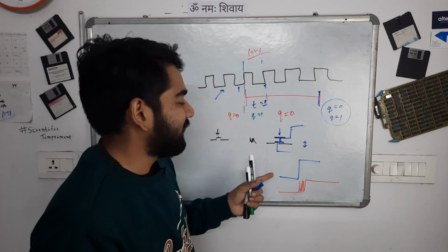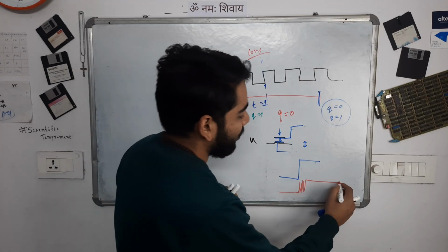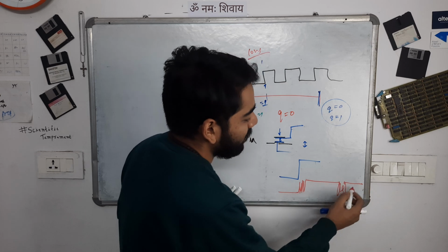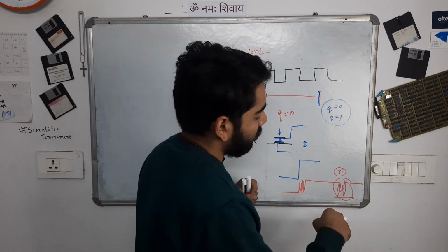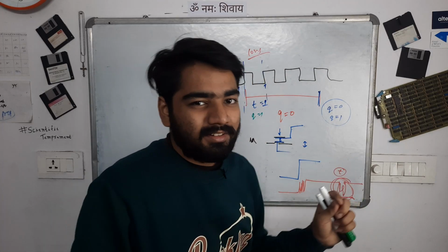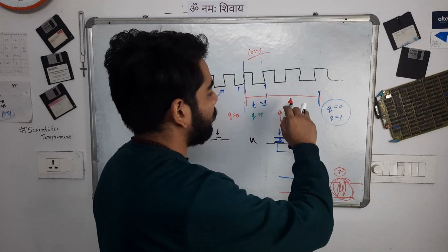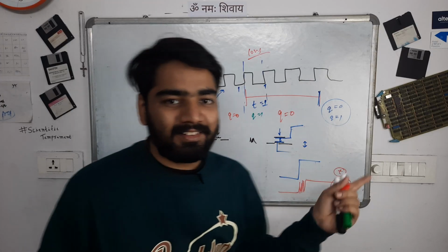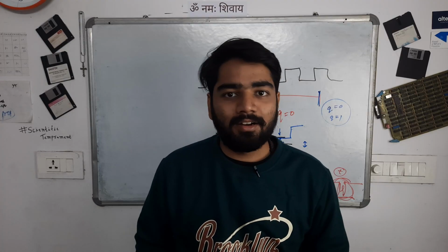So that is one case. Another case is that when I lift my finger, some kind of debouncing can also happen over here, and you can have this toggling effect. What the value of t was at this point is again not known. So because of the combination of these two effects, we are seeing that anomaly in the toggle flip-flop output.